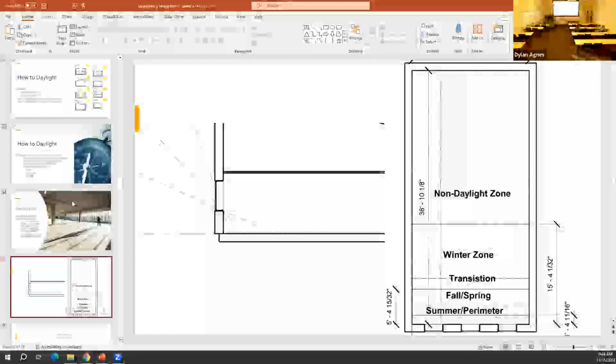And so if you have a room placed in this space, you can use the room separator to basically call out that area. It gets a little confusing on the room schedule initially, but basically you can calculate how much of the area per room that you have placed in the model to add up your IECC daylight harvesting area that you're going to get credit for.